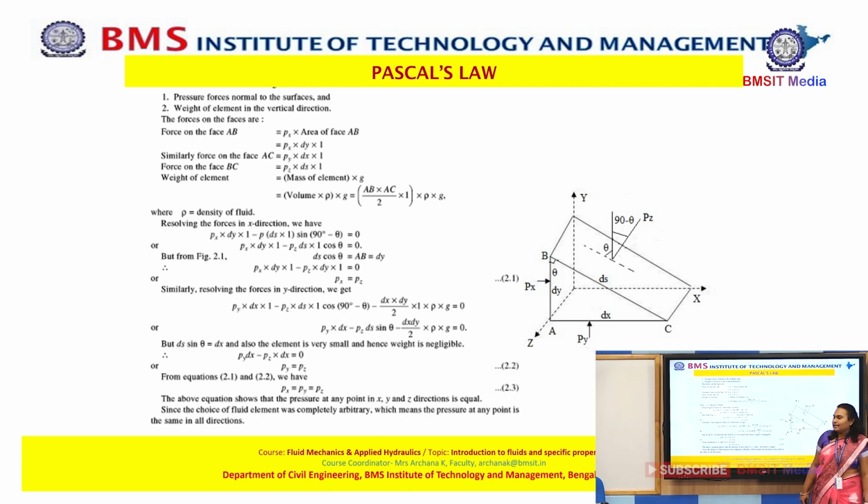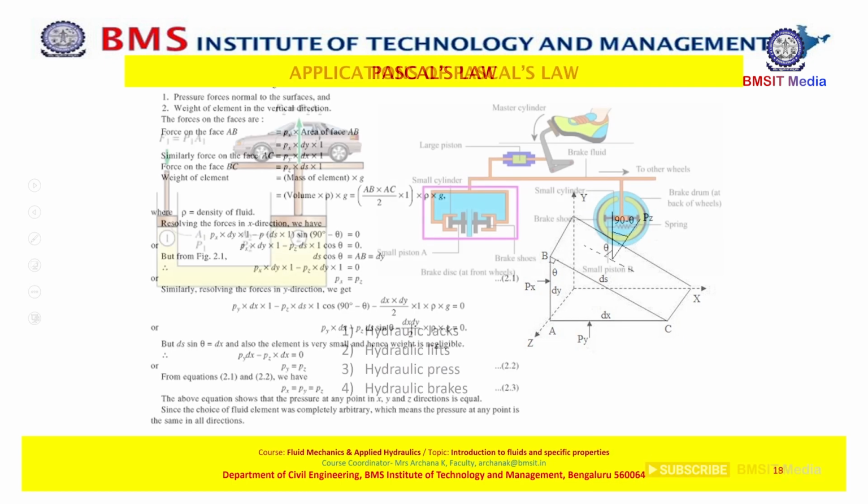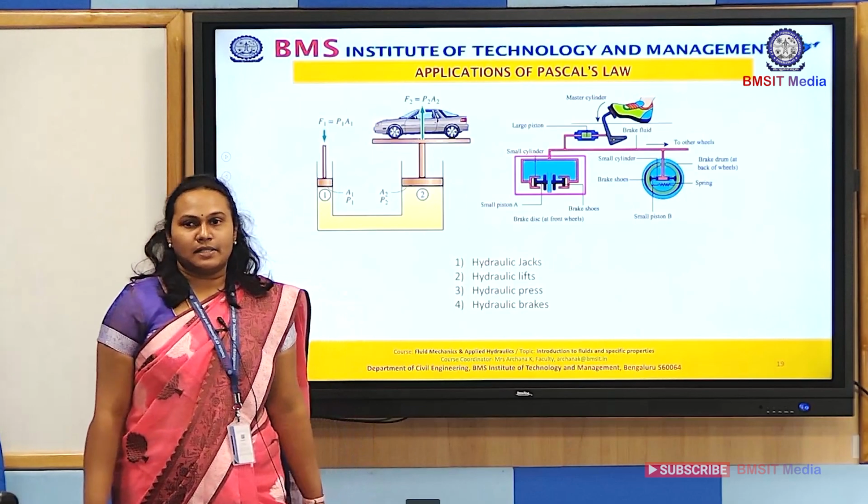equal to Pz. Seeing the equations Px is equal to Pz and Py is equal to Pz, we will end up with the equation Px equal to Py equal to Pz. Now this proves Pascal's law. Now what are the different applications of Pascal's law?